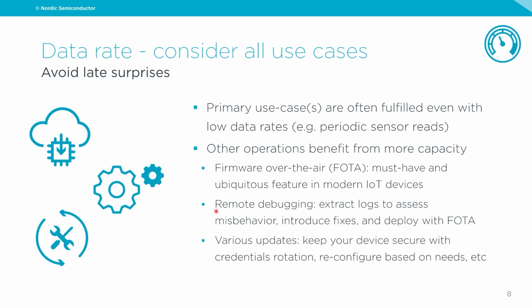Then when it comes to a bit on the life cycle and maintenance of your device, ideally you'll want to be able to maintain them remotely. So you want to do remote debugging, which means you might want to have the capability to, for example, extract the logs from your device, so you can look at what's happening and try to understand the misbehavior, introduce fixes in your source code, and get a new firmware deployed with FOTA as quickly as possible.